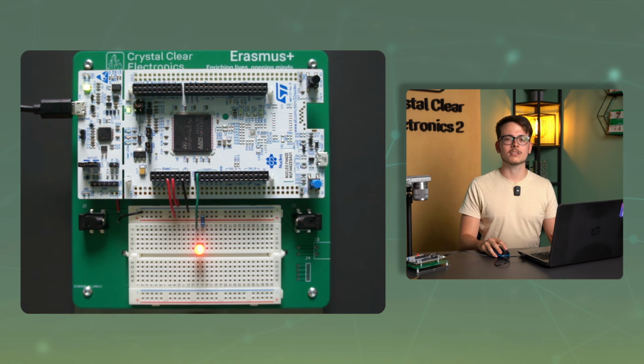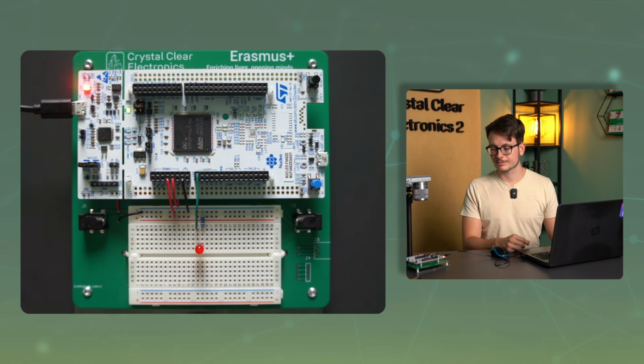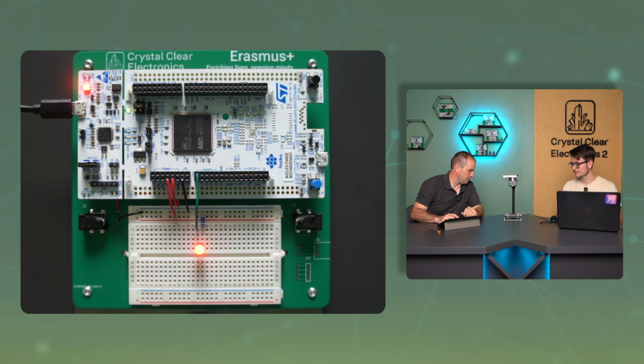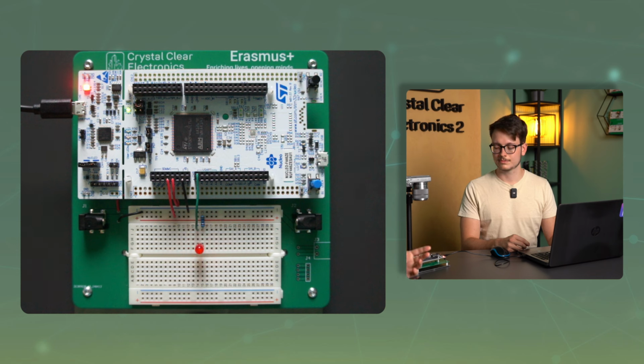I'm done with the code and I'll upload it to the board so we can see if this is what will actually happen. Now let's see. I have uploaded it. The LED is flashing, which is a good sign. 3, 4, 5. Now comes a 5-second wait. And the LED is flashing, which means the Watchdog is doing its job, so we're okay. Yes, the program has restarted.